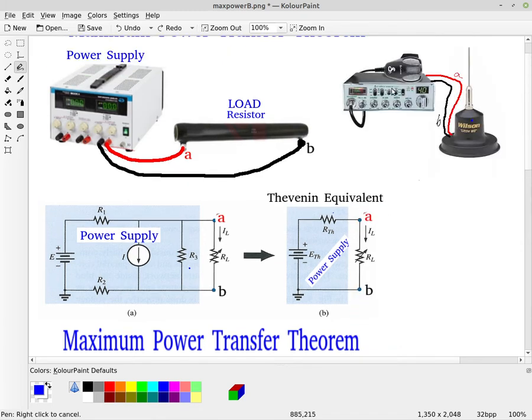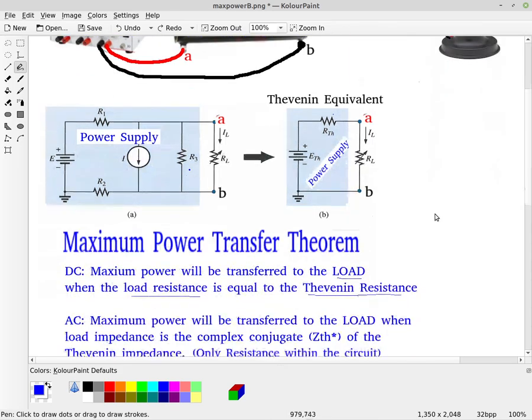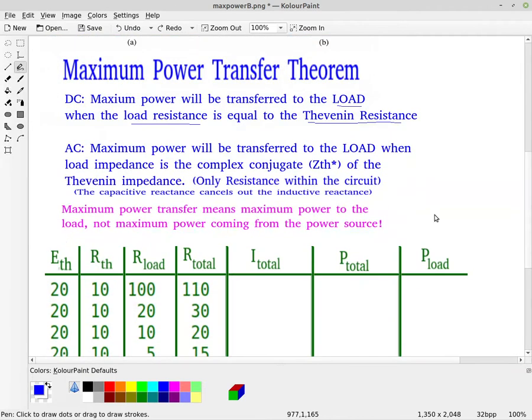Again, we can't really do much about the electronics in this radio, because if we start messing with that, then we can't actually transmit the signal the way we want to. So the impedance in here is dictated by what we need to do to actually generate a radio signal that we can send out to the antenna. We therefore need to match the antenna to our radio device.